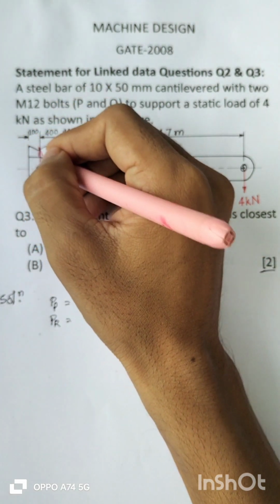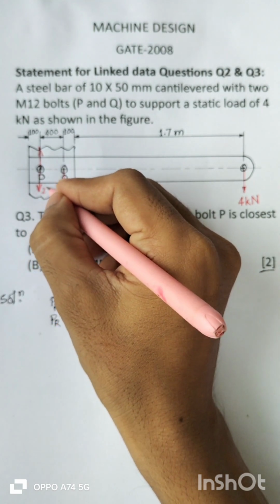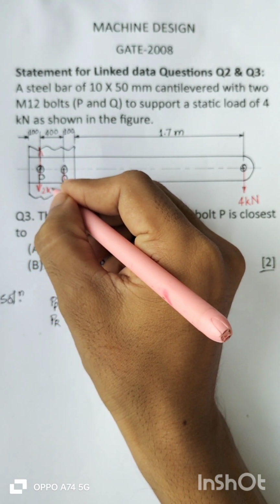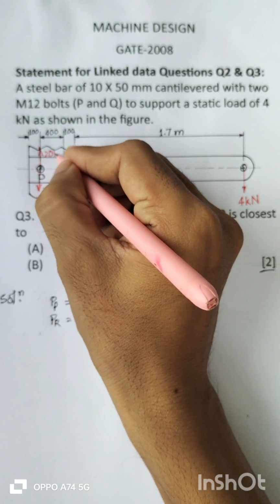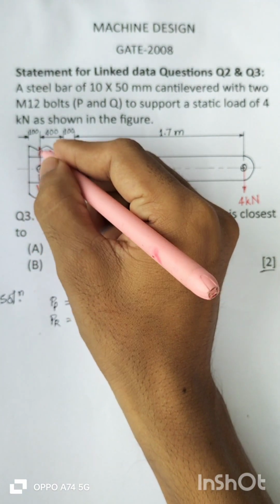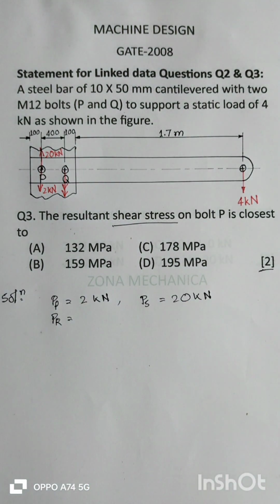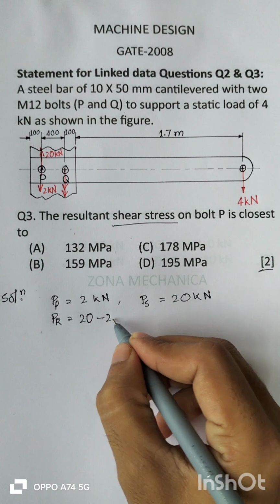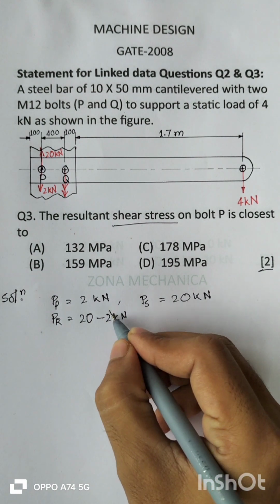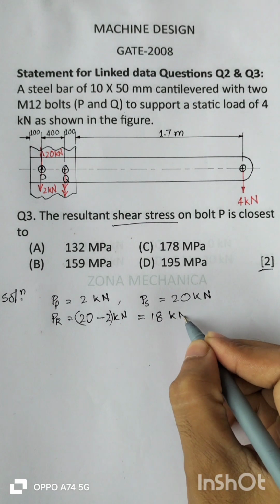Whatever it is, we are concerned about bolt P. So this is 2 kilonewton primary shear load, and this is the secondary shear load, 20 kilonewton. So these two are opposite in direction, so the resultant shearing load will be 20 minus 2 kilonewton, which is equal to 18 kilonewton.